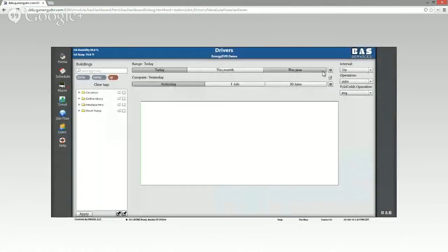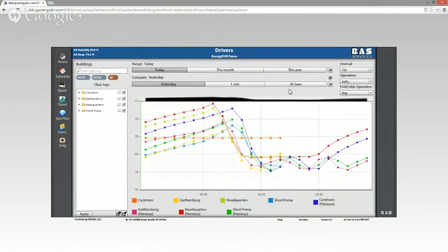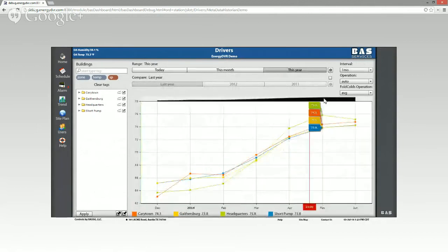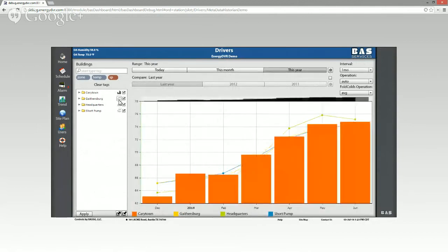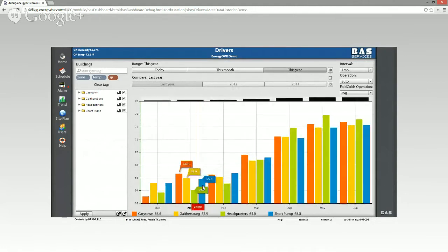The third one is the same database. We are looking at zone temperature set points. And you can do easy profiling within here. We can do this year and roll it up by month. We can look at the data in bar charts, and you can see how the zone temperature is rising within the system and what the averages of the zone temperatures are as well.